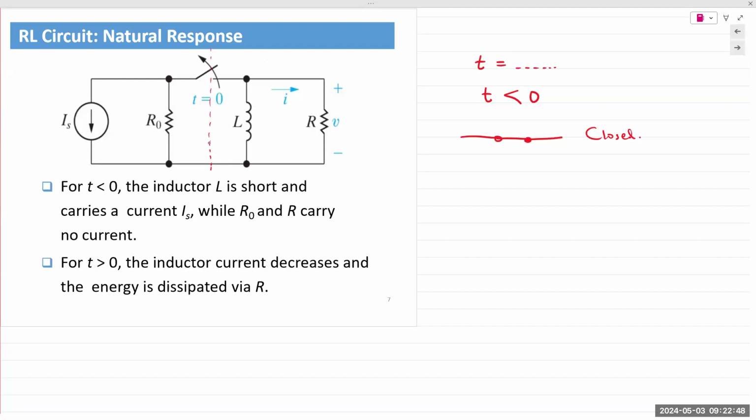So if you read the words "a long time," those words indicate that the component is at steady state. Whether the steady state could be fully charged or fully discharged. In this case, we can see that the switch was closed, and the current source was connected to the inductor. So the current source has transferred energy to the inductor. The inductor has captured all of the energy that it has the capacity to store. It has reached steady state.